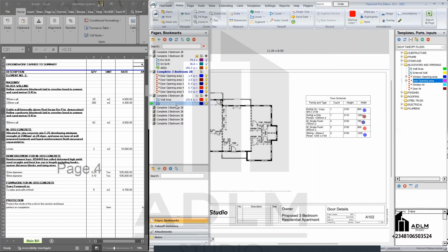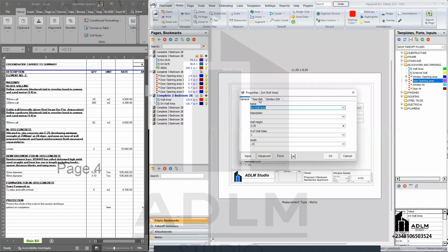So just do internal wall area. Come to door, deduct those. So you just use door 3 and door 4. That's door 3 is 6.3, 6.3 plus 5.7. As easy as this. Now for door 5, one of them is internal, one is external. So let's divide this by 2. That's plus 2.5.